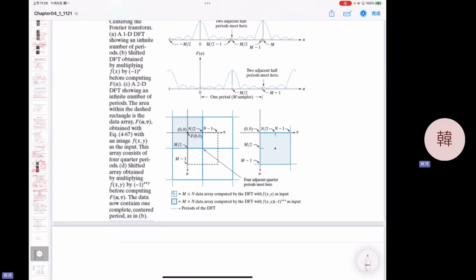You still can see some of the boundary information because it's blurring, right? It is blurring with a Gaussian low pass filter. What's the result? Like this. So some of the boundary is fine, but some of the boundary didn't change at all. You can see that all the boundary should be smooth. But if you do low pass filter with 0 padding before you process, it will become like this one. So every edge in your original image will be smooth. So you can see the difference, especially at the different locations.